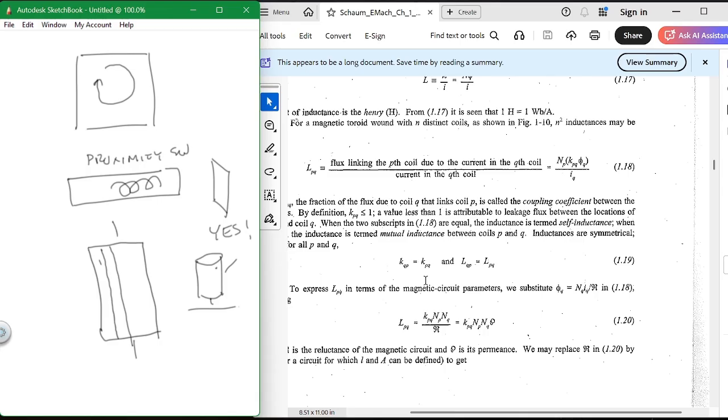Now I have a little one here that is a little toy one. It's just a little bitty one, but you can actually see it here, and there's the coil of it, and you can touch this, and you can see it actually turning on. It makes that contact change. So I'm going to pass this around. The coil is between there's pins down here, and then there's two pins up here. The two pins up here are the coil, and this is the plus and the minus 9 volts. That's a 12 volt, but it'll still work at 9 volts. You touch it between those two, and you'll actually see it change. You can hear it too. I'll pass that around. So you can use a magnetic circuit to actually do some work, and that's what that is. Okay. So that's that one.